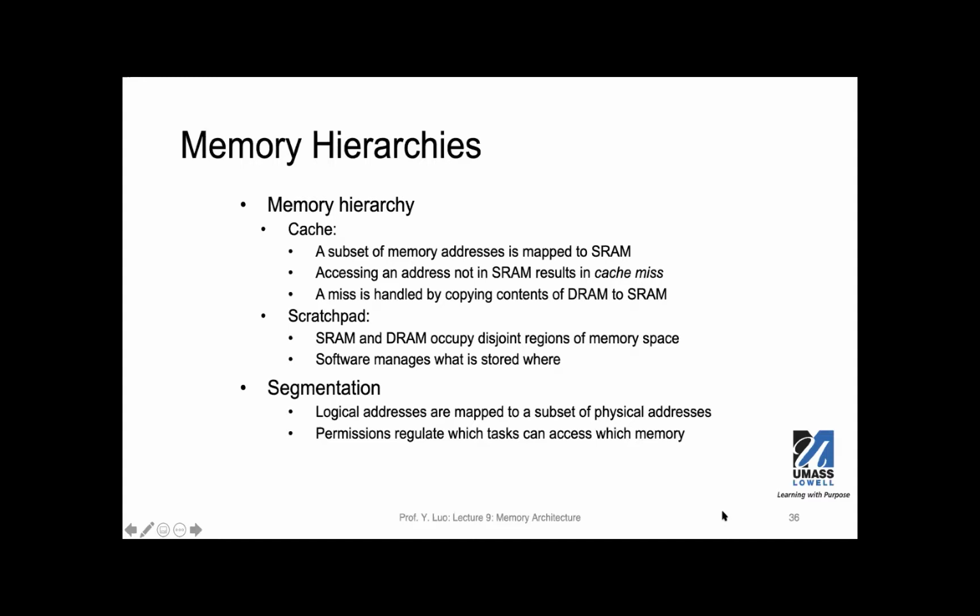That's more common in higher-end embedded microprocessors. A cache is a subset of memory space that's mapped to SRAM. Because it's based on SRAM, its access speed is fast, but the size of the cache is relatively small.